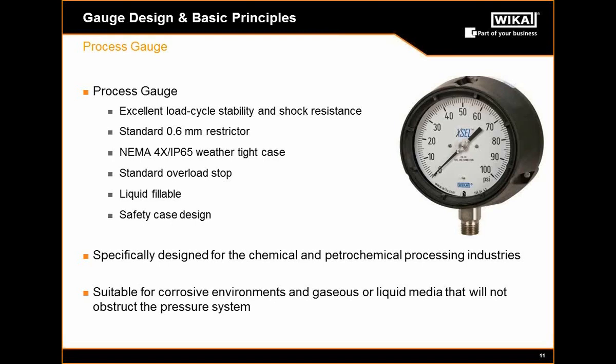The case comes with a NEMA 4X or IP65 weather-tight seal, and what that's going to do is give you a lot of protection from environmental contaminants. There's a standard overload stop to prevent the gauge from overpressurizing beyond the maximum pressure that it's been designed for. Now that doesn't prevent failure necessarily, but it is designed to help, and I'll discuss that more later. All of these cases can be liquid filled, further protecting the gauge's internal moving parts through lubrication and also protection from vibration. And finally, they have a safety case design.